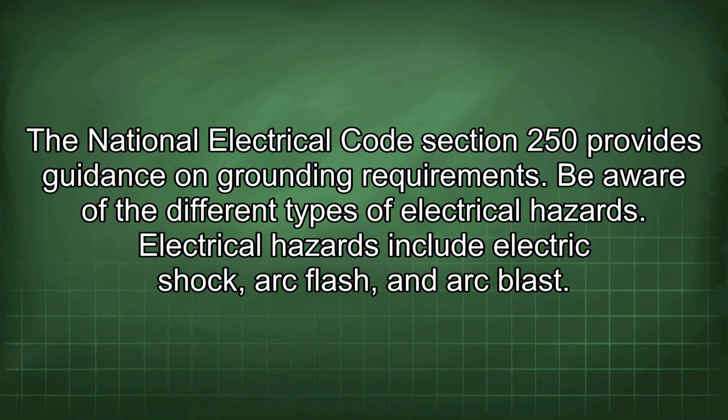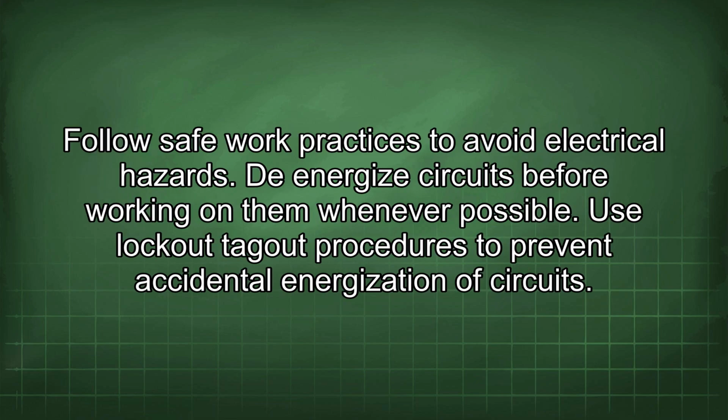Be aware of the different types of electrical hazards. Electrical hazards include electric shock, arc flash, and arc blast. Follow safe work practices to avoid electrical hazards. De-energize circuits before working on them whenever possible. Use lockout-tagout procedures to prevent accidental energization of circuits.